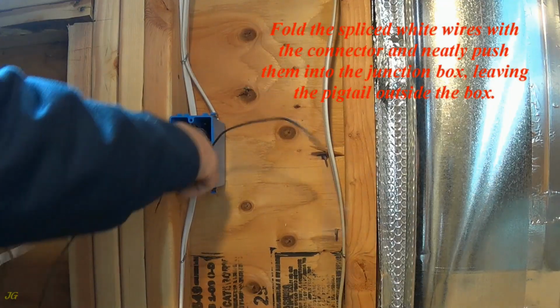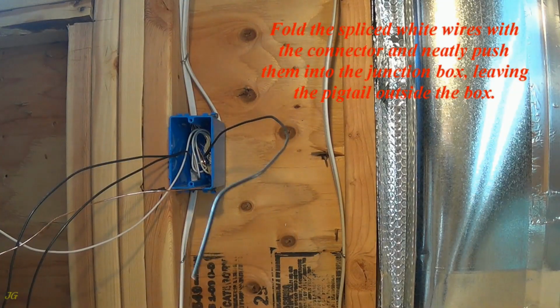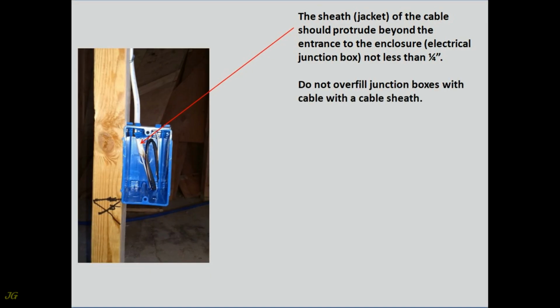Fold the spliced white wires with the connector and neatly push them into the junction box, leaving the pigtail outside the box. The sheath, jacket, of the cable should protrude beyond the entrance to the enclosure, electrical junction box, not less than 1/4 inch. Do not overfill junction boxes with cable with a cable sheath.